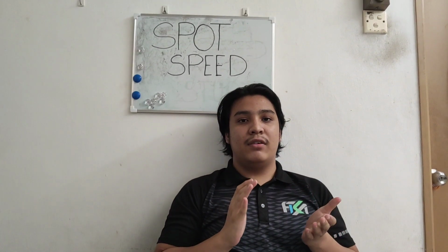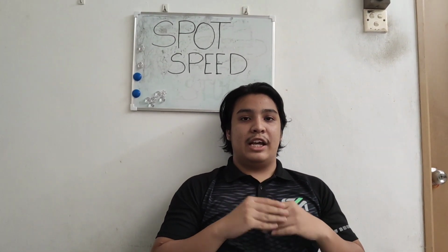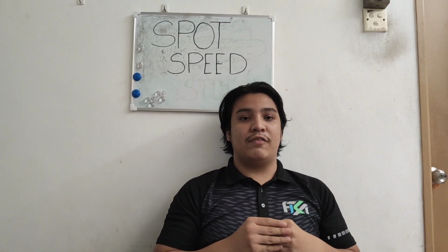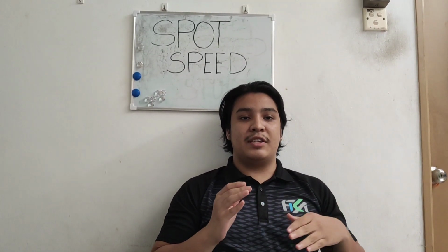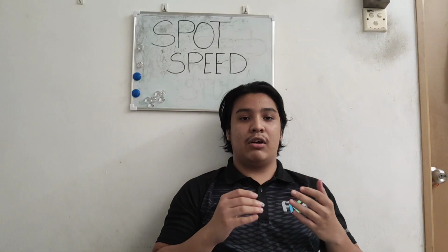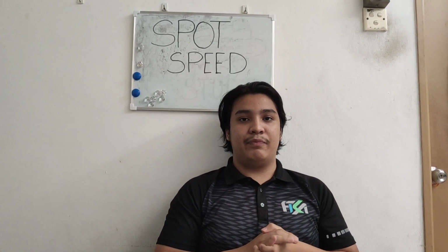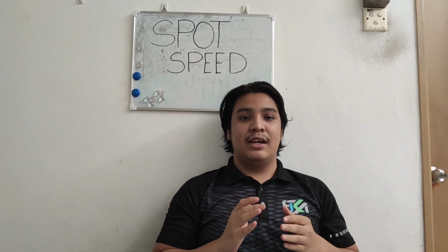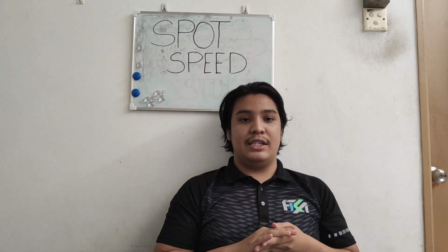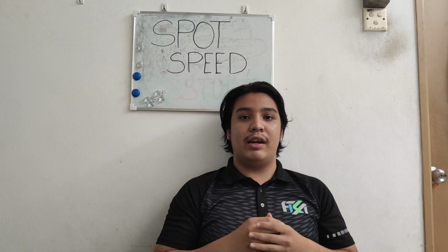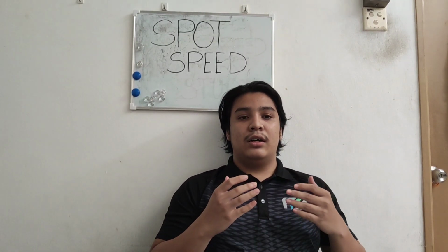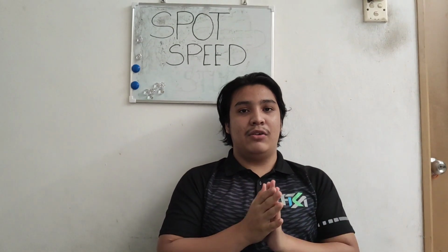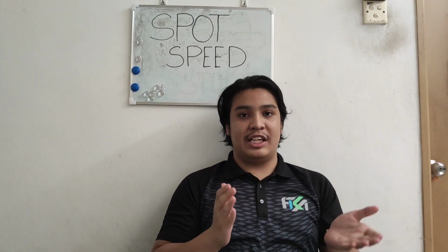The objective for this experiment, the first one, is to establish the speed distribution of traffic stream at a specific location, or can be called basic speed data. The second one, to determine vehicle speed percentiles via speed trend analysis, which are useful in speed-related decision making.